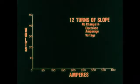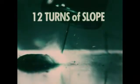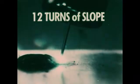Adding excessive slope, as much as 12 turns of slope, achieves a lower short-circuiting current, and the time of electrode contact in the weld puddle increases. Only slope, not voltage or amperage settings, have been changed. Note the stubbing action of the electrode. This is due to a severely limited amount of short-circuit current. There simply is not enough heat to properly melt the electrode or the base metal. Even this greatly reduced amount of current does not return to the point of short circuit quickly, since the response time of the current has also been drastically cut back.